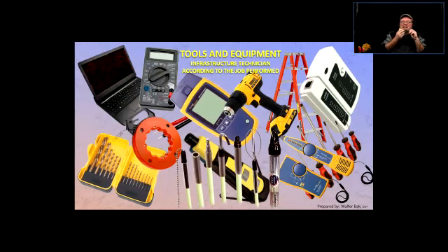And you need that hammer action on the drill if you drill into harder surfaces such as concrete. Okay, you would not use a hammer drill if you're drilling into steel because you're just going to damage the drill bit. Right? After about 30 seconds, you have no drill bit. You're just going to dull it.